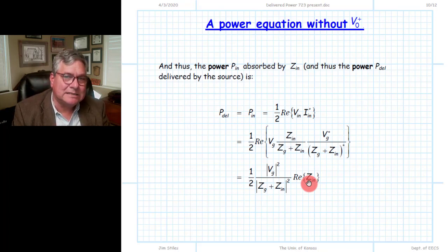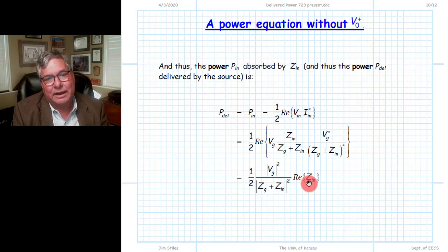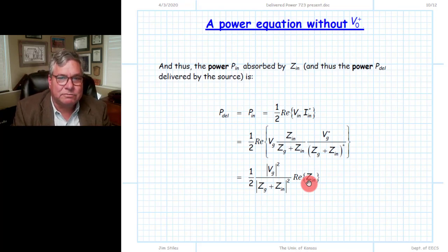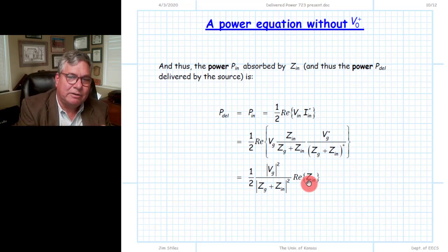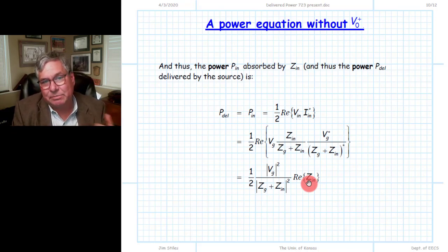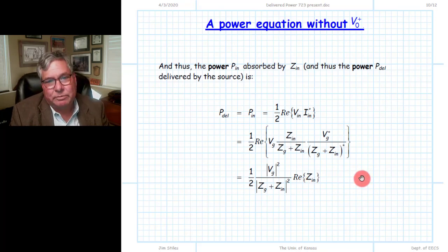And so that is typically, again, the strategy we use for problems like this. We go through and we draw a plane right after the source. We take everything to the right of that plane, which is a passive structure, and we try to crush it down into an equivalent circuit, a simple lumped impedance, that is the input impedance. And once we do that, then again, finding the current and voltage and power is a very simple circuits problem that any freshman electrical engineer would be able to achieve.